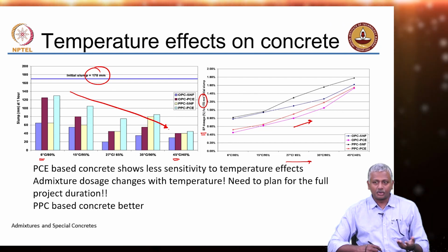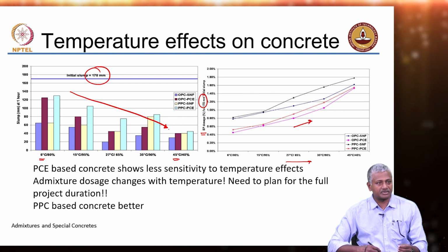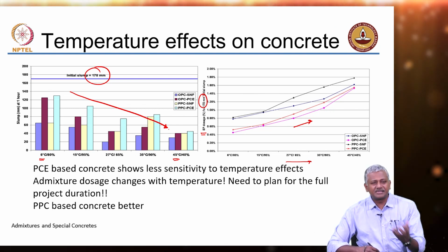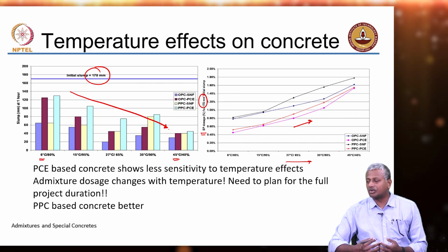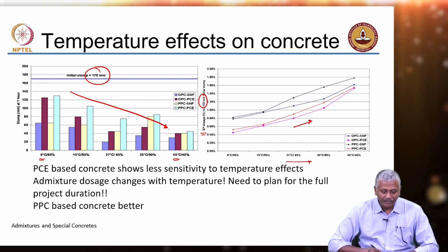Okay. Now, assuming that you have done your design with appropriate moisture corrections to ensure that the moisture for absorption with the aggregate has also been added, still it is not very easy to maintain the same level of water in your system throughout the process up to 1 hour or maybe even up to 2 hours.